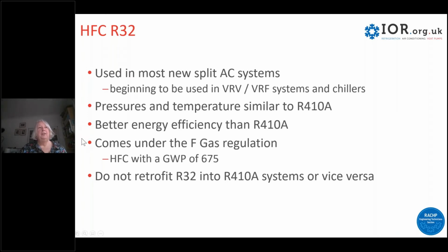Unlike some of the other flammables, it comes under the F-gas regulation. It's got a reasonably high global warming potential, so you couldn't really say that it's a totally long-term refrigerant. And it's important that you don't retrofit R32 into a 410A system, or the other way around.